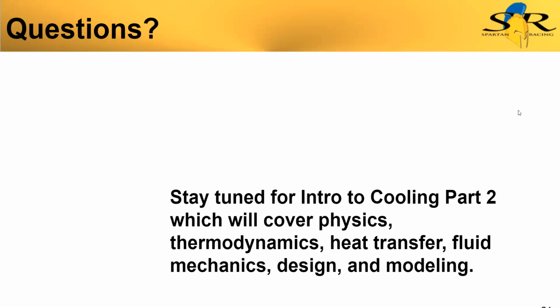Right. It's in relation to the other components. It's not going to matter, because it's going to have the same pressure drop across that component, no matter whether it's before or after those other components. But it does matter in relation to the atmosphere, because it's a closed system. So the absolute pressure will be different in different parts of the system. But that's in relation to the inside of the system and the outside of the system, rather than the inlet of the component and the outlet of that component.